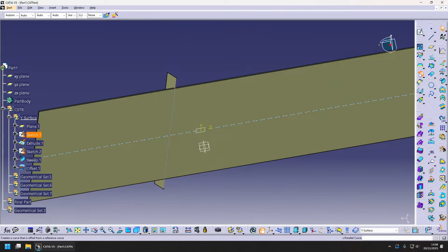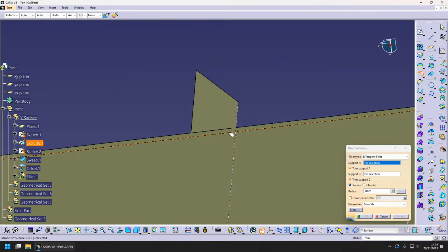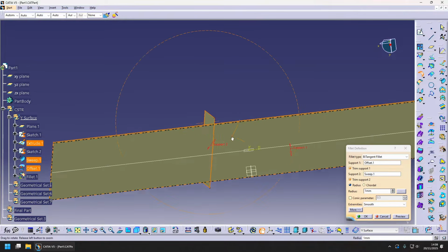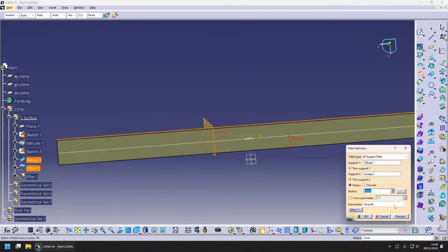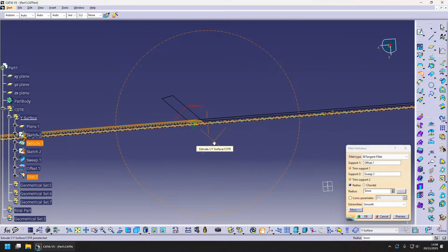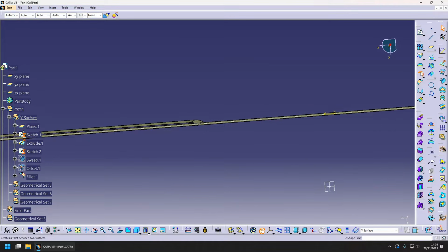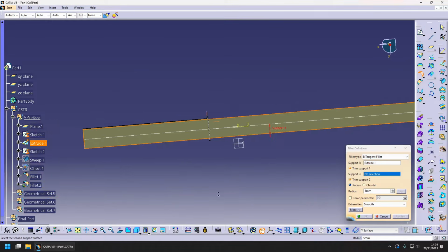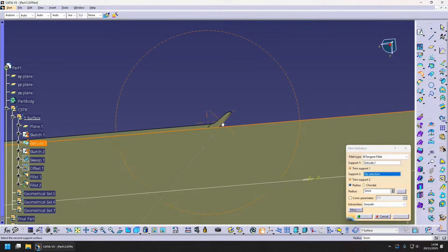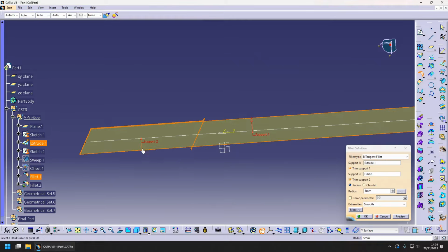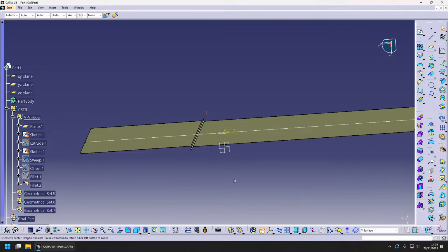And afterwards, I'm just gonna fillet these together. This way of creating joggles is kind of like an algorithm, so make sure you remember this really well. Okay? And that's how we created this little joggle step here. So remember this procedure because we're gonna do it a lot. Line sketch, sweep, offset, and fillet everything together. That's how we create joggle steps every time. Make sure the orientations are right. Okay, good.